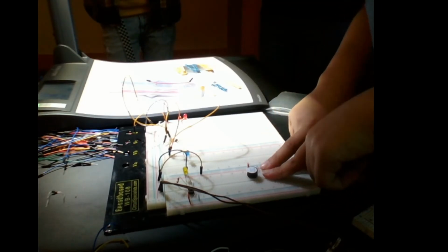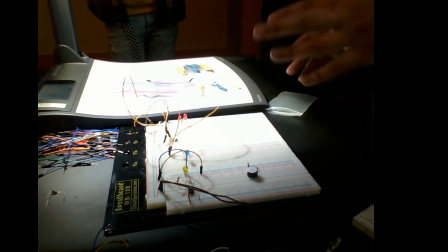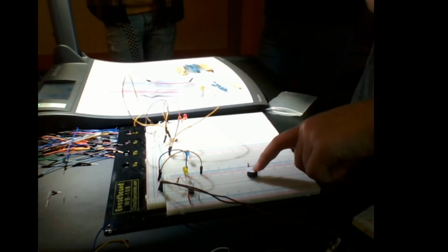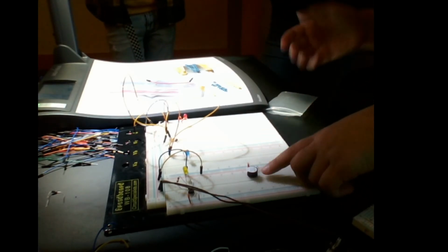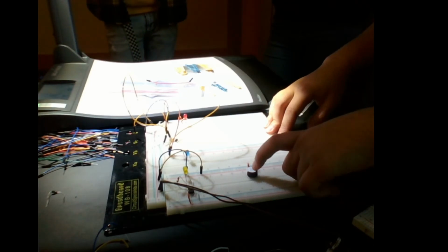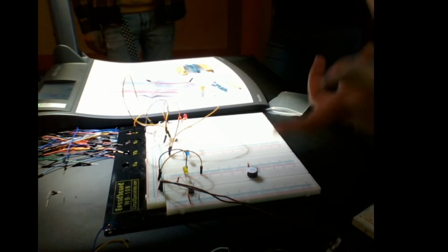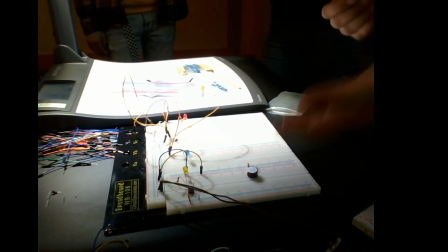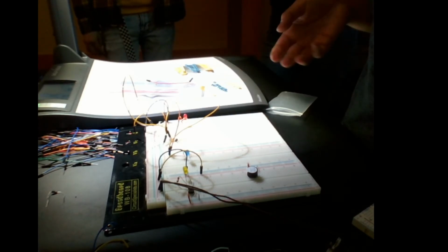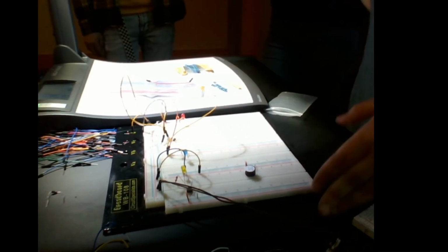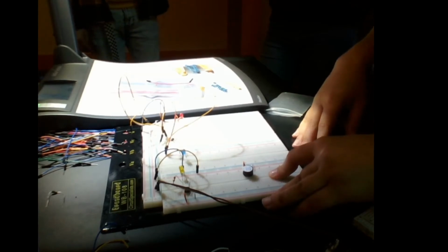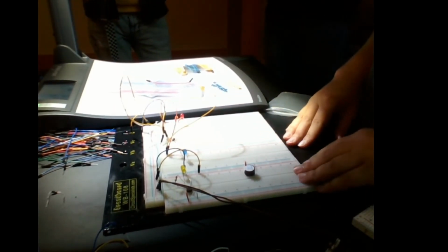And it's very, very simple to wire. You don't need any resistors in between or anything like that. And if you actually use this with something like an Arduino or Raspberry Pi, you can control what frequency it outputs, so you can put higher pitches or lower pitches based on what you want it to do. The applications of this are usually in your laundry, your washing machine. It has a buzzer when it's done, right? Same technology. If you want an indicator that's not just a visual indicator like an LED, you want a sound indicator, that's when the buzzer would come into play.